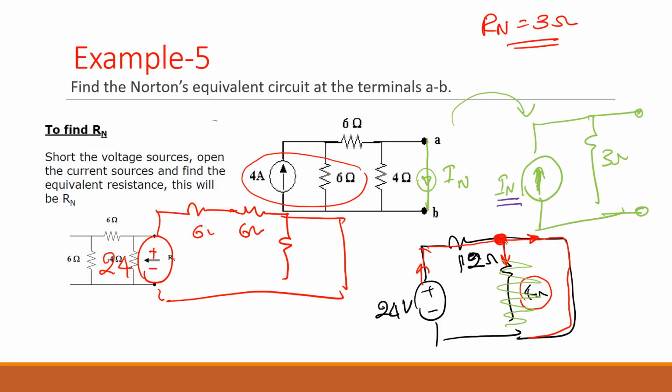So you can get rid of this. You don't need to have this one. Makes sense? So your circuit will look like this. Why? No current will be going through the 4.